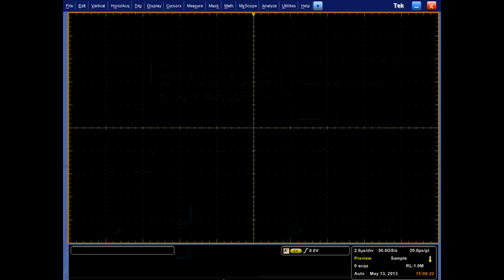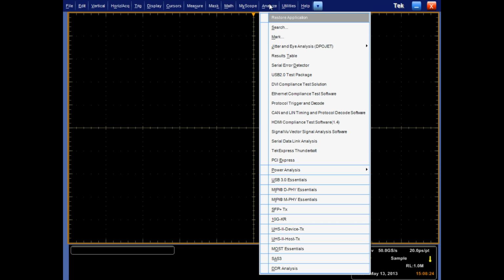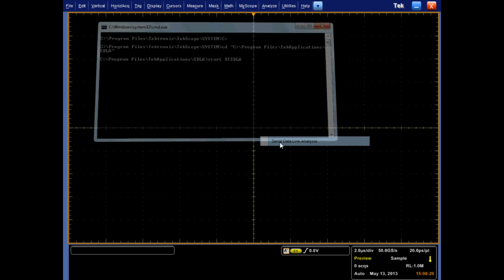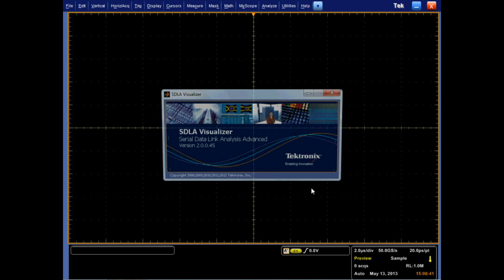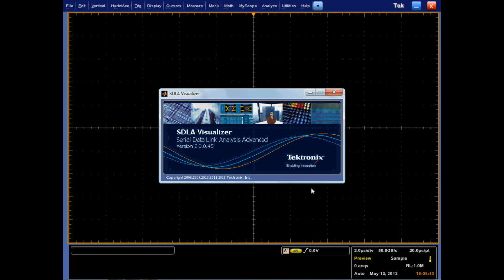Shrinking geometry of today's devices results in many challenges for testability. One key challenge is the ability to probe the signal at the desired test point. Probing in many cases happens on a via that is located away from the termination point. This causes reflections on the signal at the probe's location. Since the reflections are not present at the physical test point, the need is to remove them in order to simulate probing at the test point.